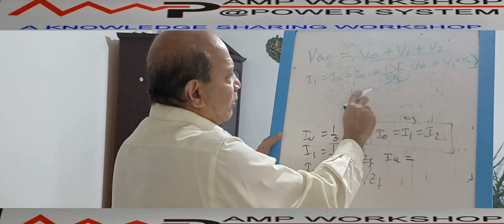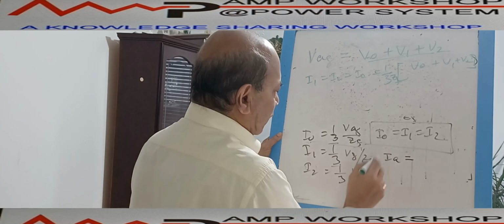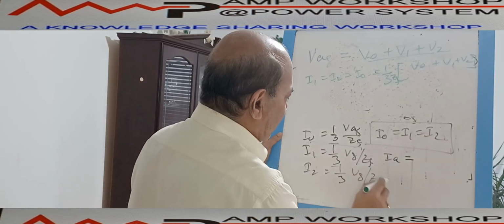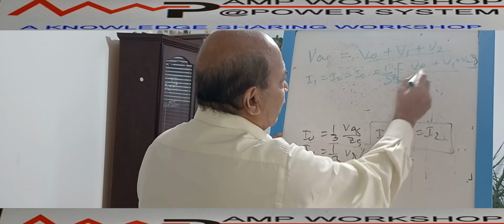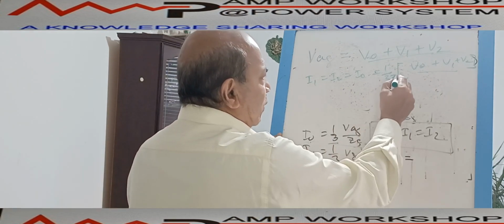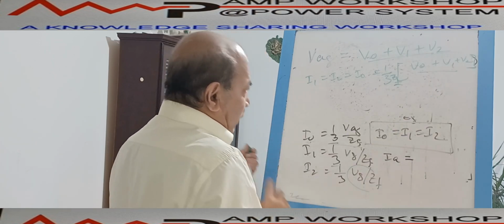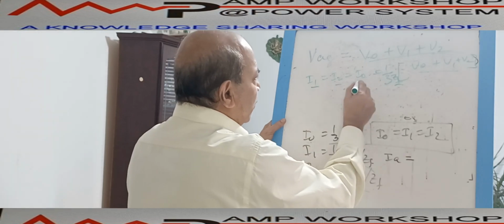I1, I2, I0 equals how much? 1/3 of ZF. So 1/3 of VAG by ZF. If we put VAG equal to this, then I1 equals I2 equals 1/3 of VAG by ZF. So we are getting I1 equals I2 equals I0 equals 1/3 of ZF into VAG, right? Now you see here another way. This is one expression we are getting, and another expression we are getting I1 equals I2 equals I0.